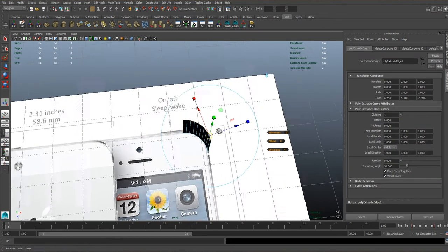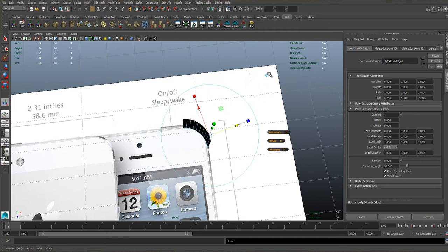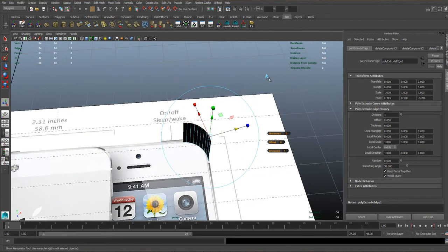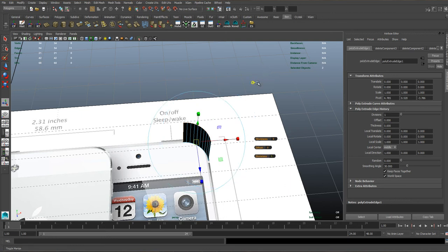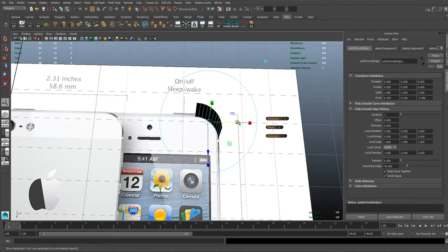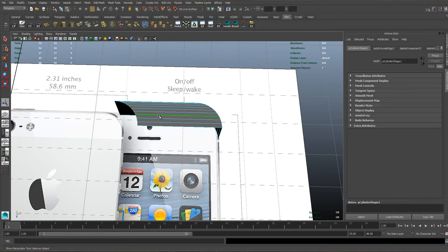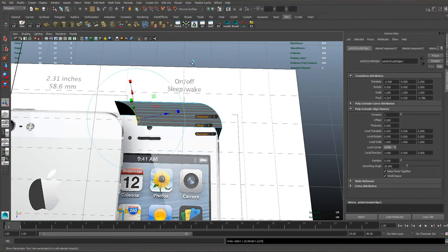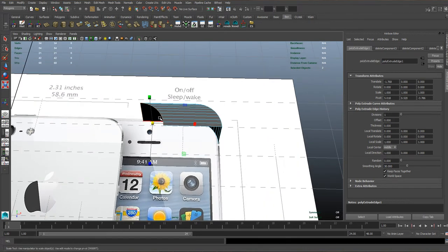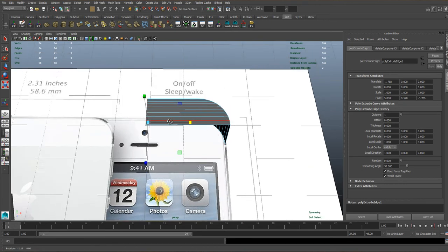And obviously before we extrude, we need to make sure we click on the Align or Snap to Grid button there. It looks like a power button. I'll probably refer to it as a power button later. So click on that so it turns yellow, and then you can extrude using obviously this arrow here to the left. And I'm not too fussed at the moment about how far along we drag this, but I do need to flatten this edge here. So I'll get the selected edges and click on R to resize, and just resize them in. I can do the finishing touches to that later.